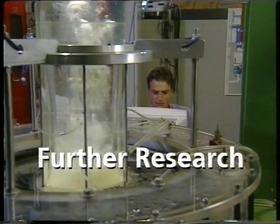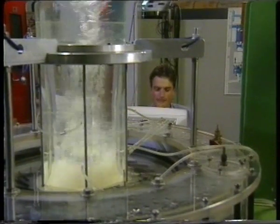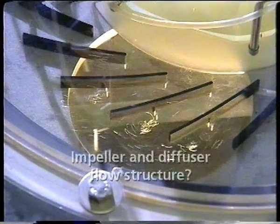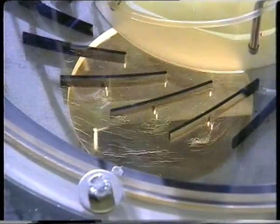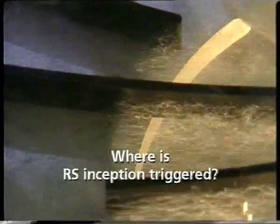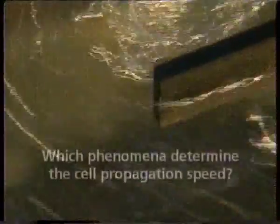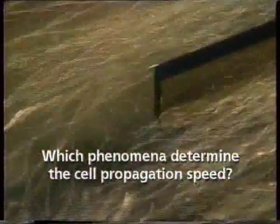In order to prevent such pulsating flow phenomena from occurring in helicopter engines and other compressors, further questions have to be answered. Such questions are: what are the details of the impeller and diffuser flow structure? What's the nature of the instability that triggers rotating stall? What flow processes determine the propagation speed of the rotating stall cell?